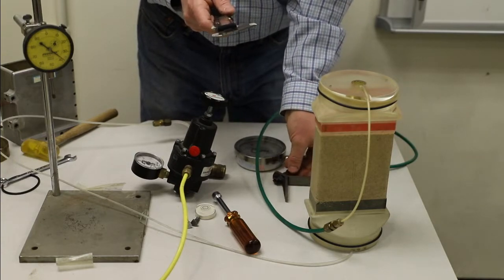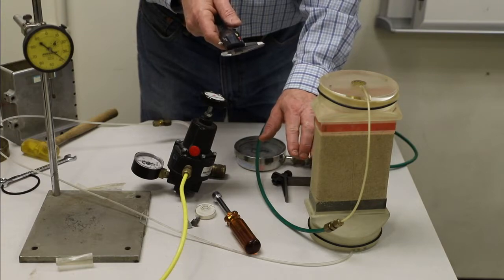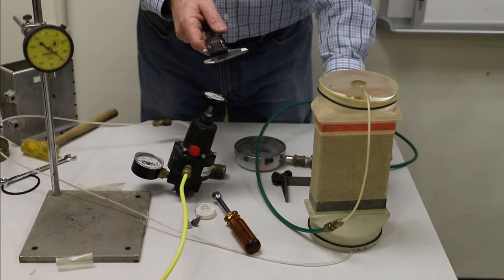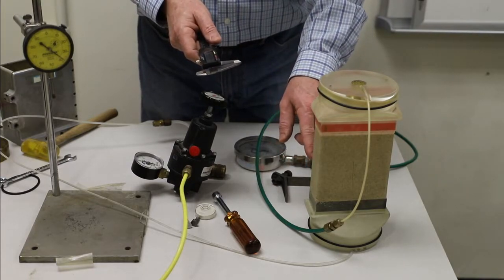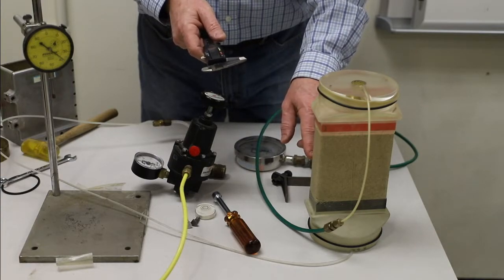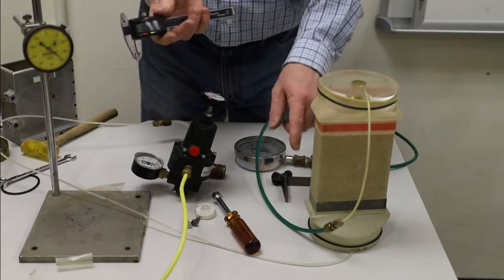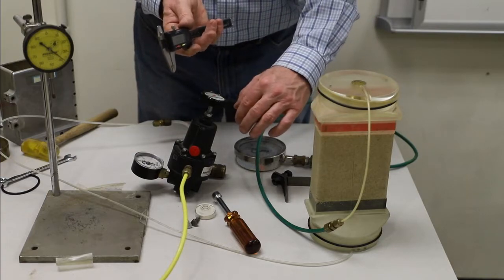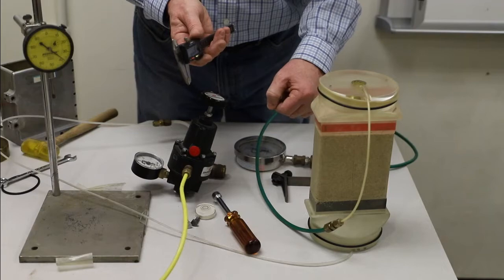And so to get the cross-sectional area of the specimen as a whole, we're going to multiply the width times the length, but then we have to subtract little squares with a side length of the radius. So we're taking out a square from each corner, and then we're adding back in a quarter of a circle that has the dimension of that radius.